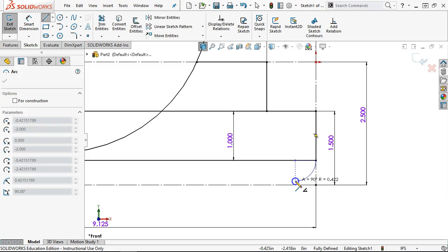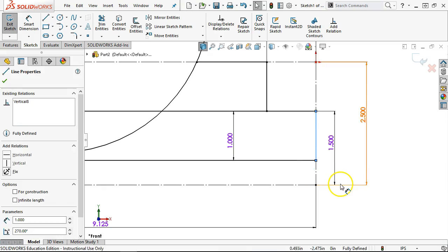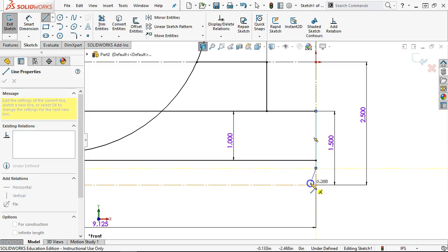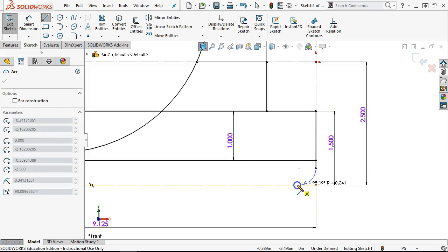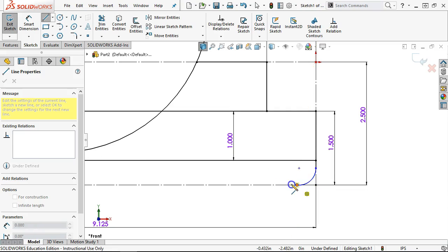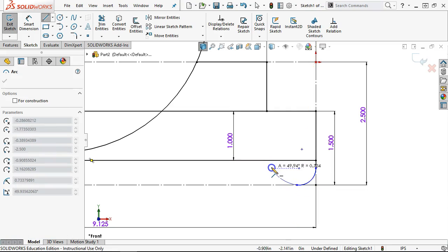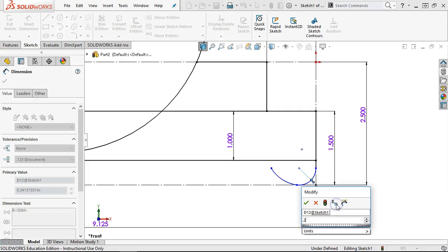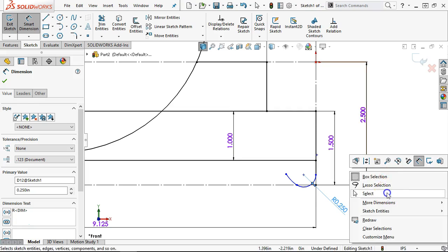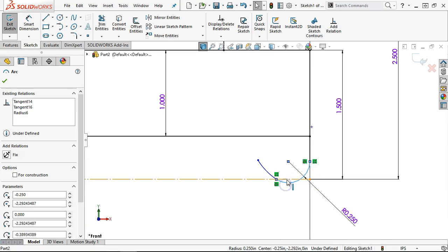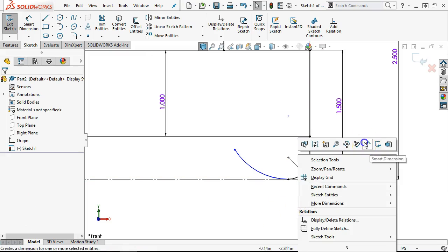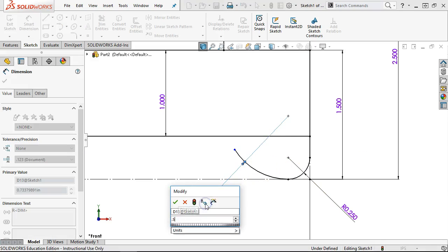We can come back with a tangent arc. Oh, I didn't carry that one far enough, so Control Z, Control Z, undo to the point I can get back to that arc. And then we'll bring another tangent arc off. So 0.25, we'll let that one shrink. It's automatically tangent to the start, and we'll make it tangent to the bottom and overall. 0.5.